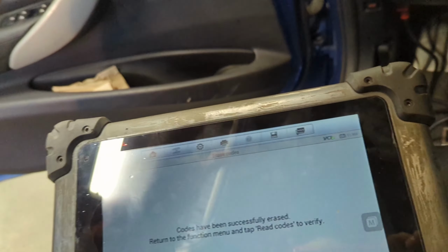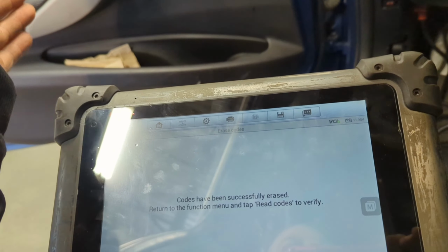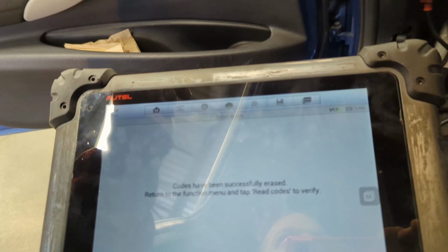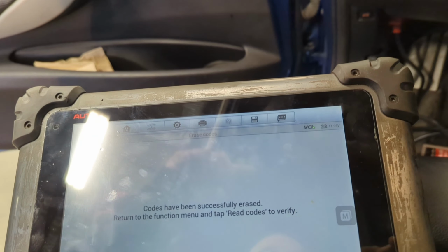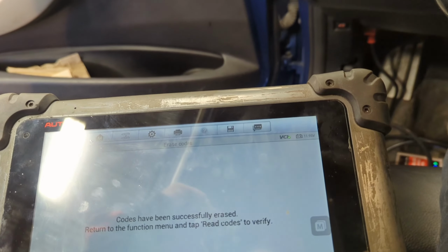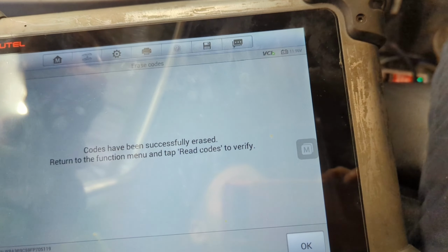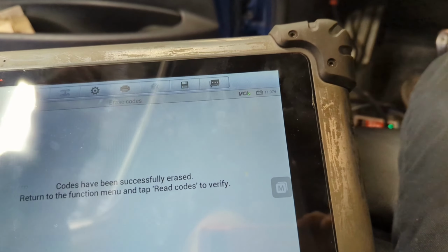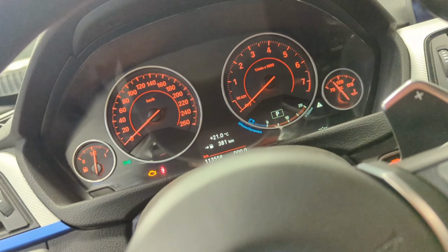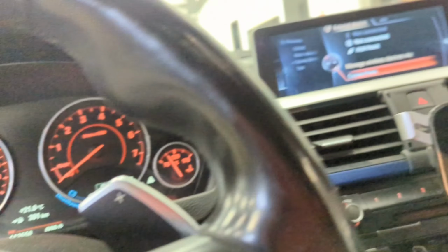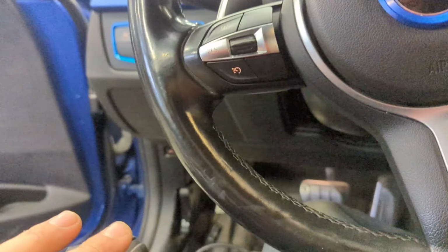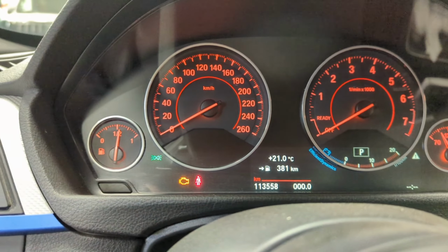All right, I had an airbag code that was on, saying that the resistance was too high. Why? Due to the fact that my connection wasn't good. From there, I went and grabbed my decade box. I'm using my decade box right now in order to create the resistance for the system. I have it set up to about 2 ohms. And as we can see right now, my airbag light is off.